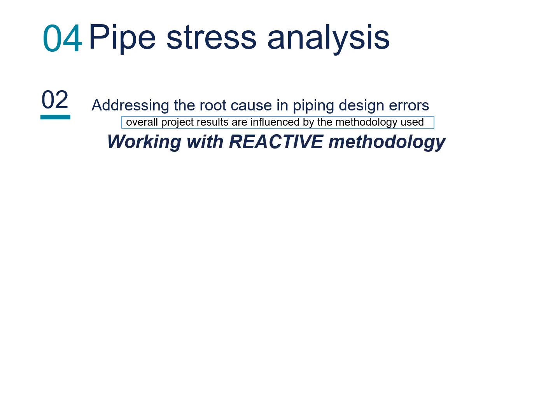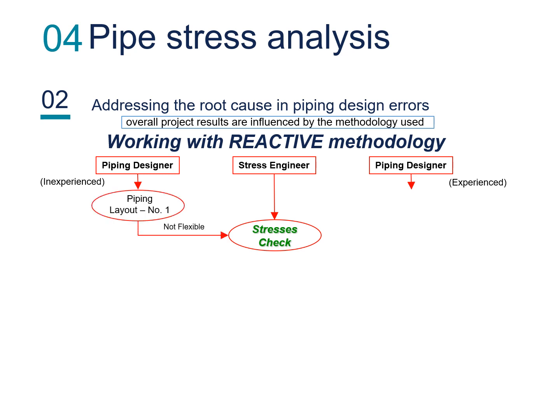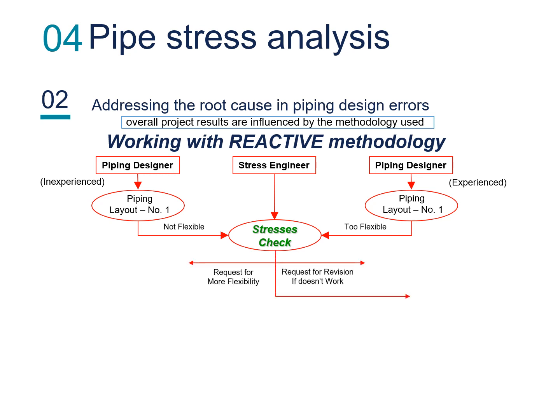In working with the reactive methodology, the stress engineer is actually placed in the position of design verifier. Therefore, he will be verifying the designs that could have been produced either by an inexperienced designer or by an experienced designer. The design produced by an inexperienced piping designer usually comes for stress verification with insufficient flexibility. On the other hand, a design produced by an experienced piping designer would come for stress verification and will be too flexible.